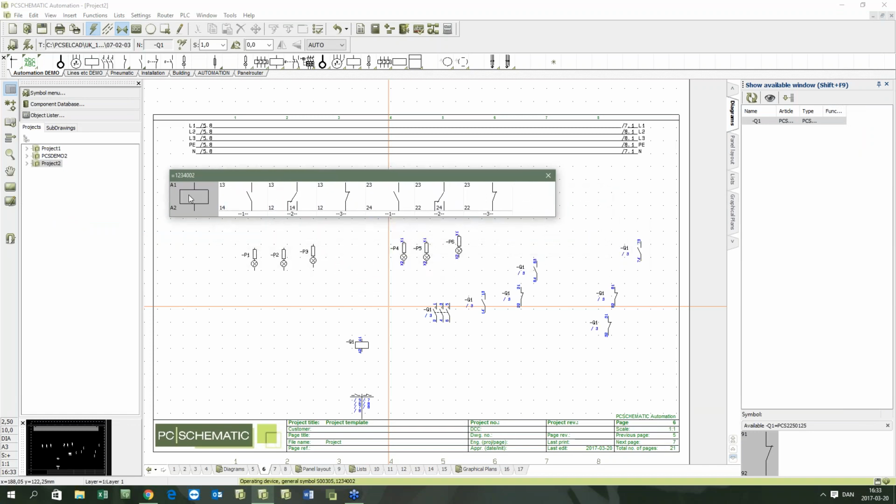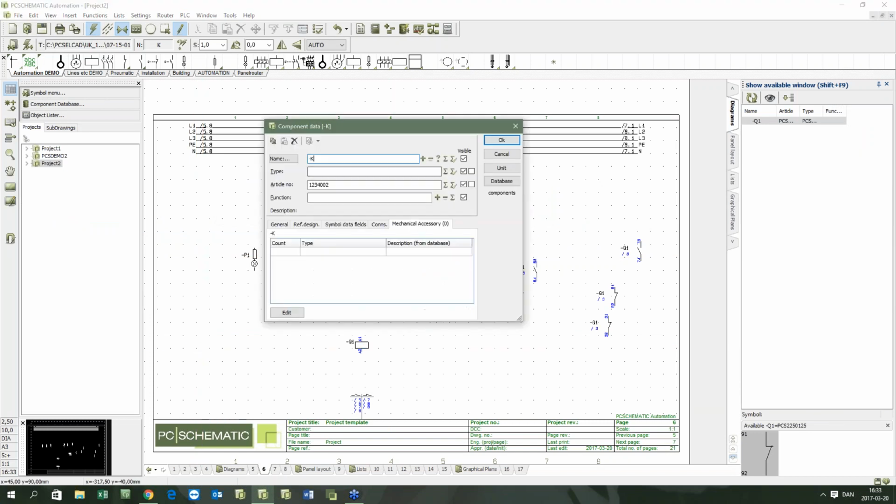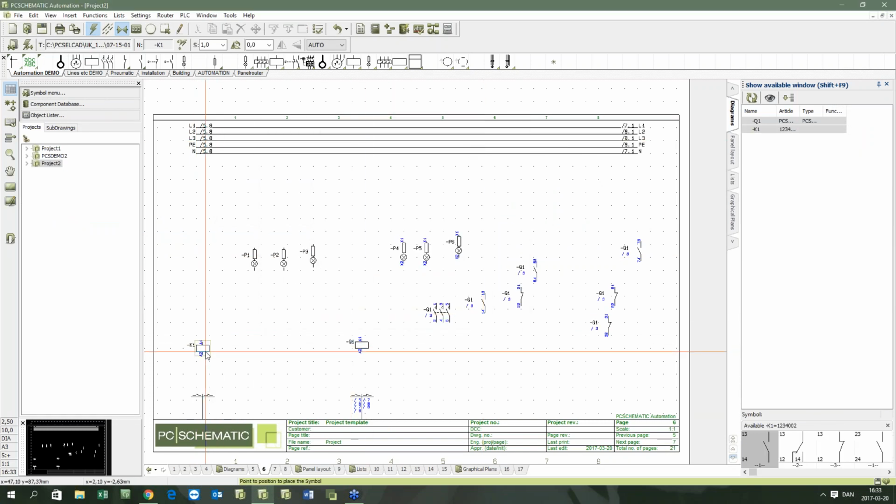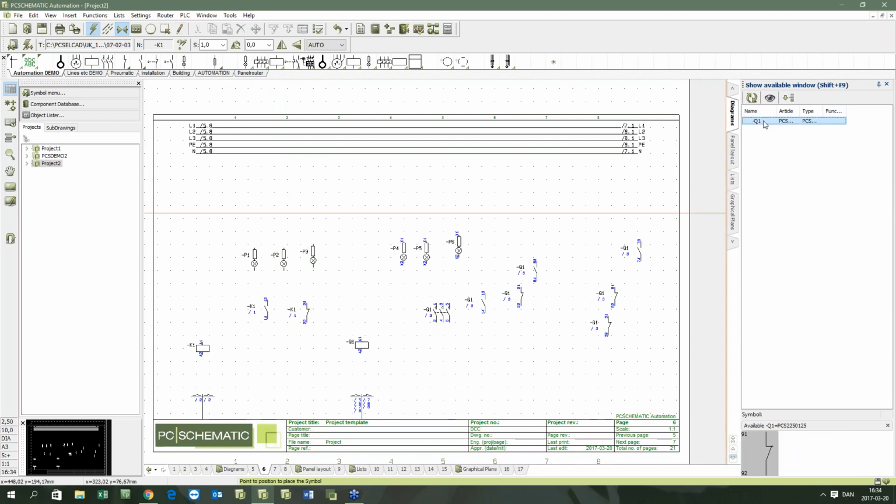Because what I did was to say my new contact has an activation coil. That's pretty normal, no problem about that one. But on the first position I can select between 1314 or 1312 or 1214. So if I go in and take this one, option 1, I'll click here, and then that's gone. And then you can see set number 2 I have here, and then I can go in and say I'll just have this one, and then take it here, and then everything is gone because this was the first one I had here. But then I only placed those 2 contacts from it.